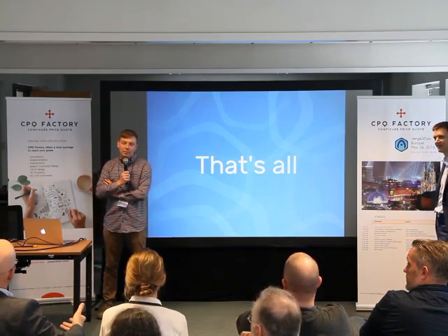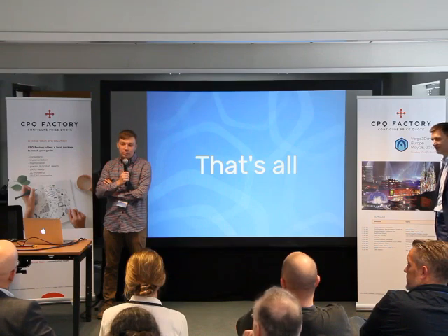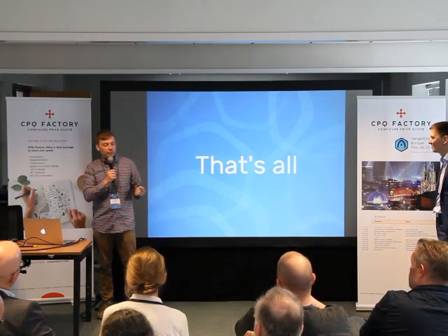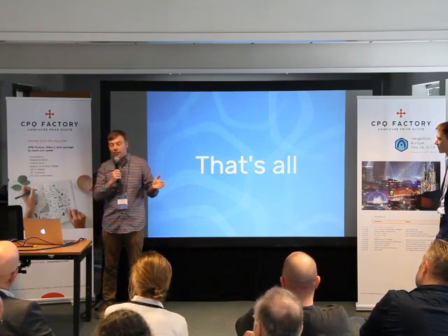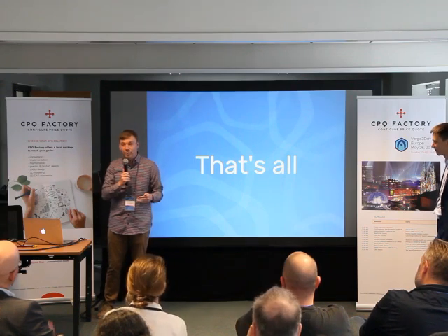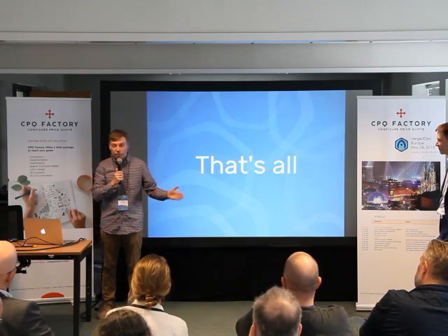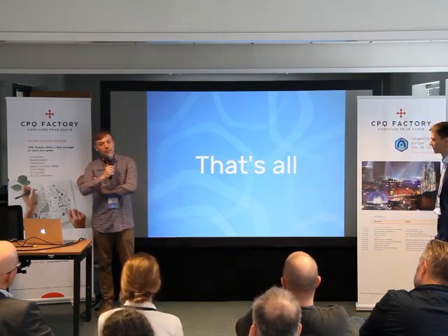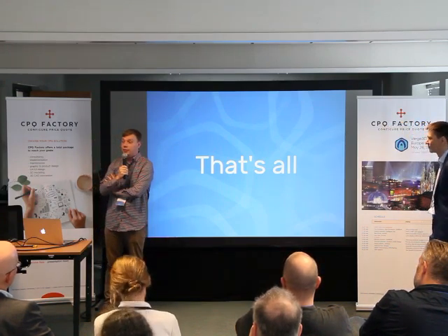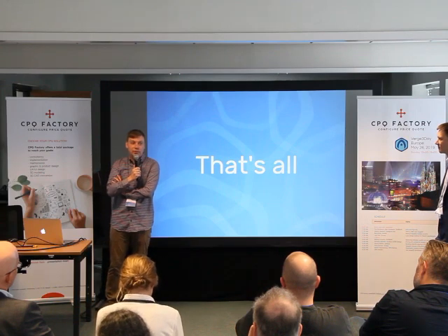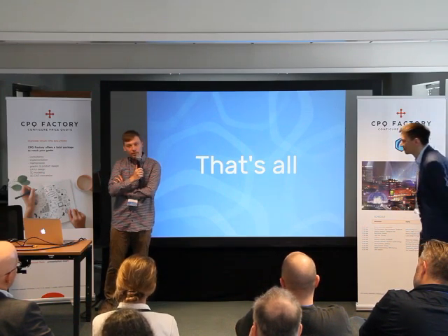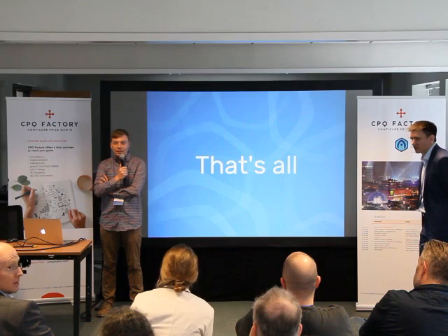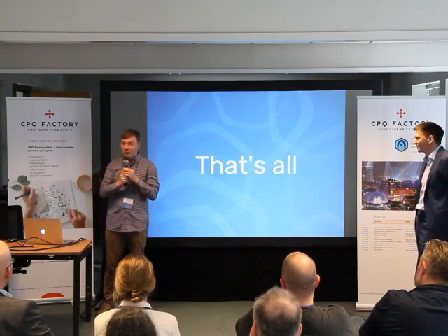How much is the penalty there? For example, if you have 10 objects with the same material, you will have 10 different shaders. It will render 10 times at the same time. If it's a really complex shader, it will extremely slow your rendering. I made such an optimization for your scene.